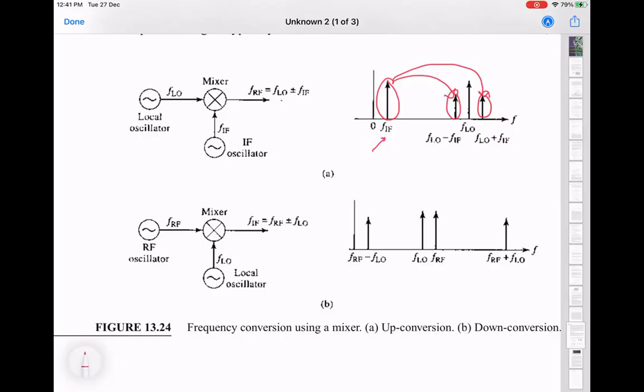FM is 100 megahertz, right? But that is a slightly different kind of modulation. It's phase modulation or frequency modulation. But for that also, you need some kind of nonlinear system only. But the point is that now the 20 kilohertz audio information has been moved from 20 kilohertz up to some higher frequency, which can then be transmitted more easily. And then you can recover that.